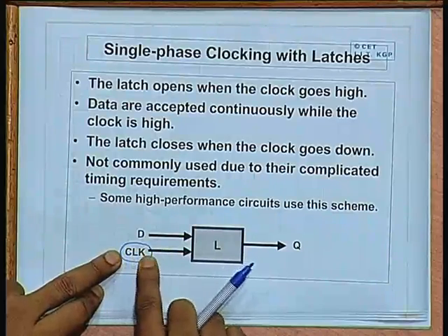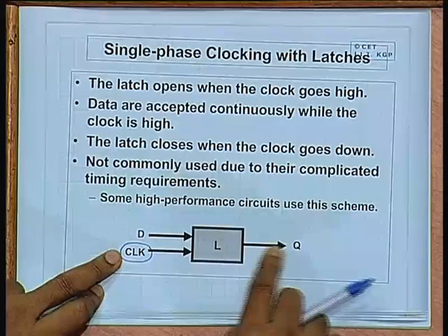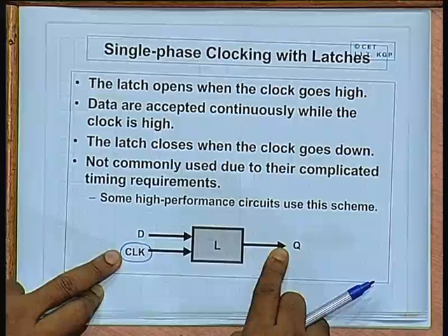There these latch based circuits work better, because when you have edge based clock circuits, you are tied by that clock period, you cannot do anything faster than the clock period. But if you have this kind of latch based circuit, as long as the clock is high, any change in the input will propagate to the output.